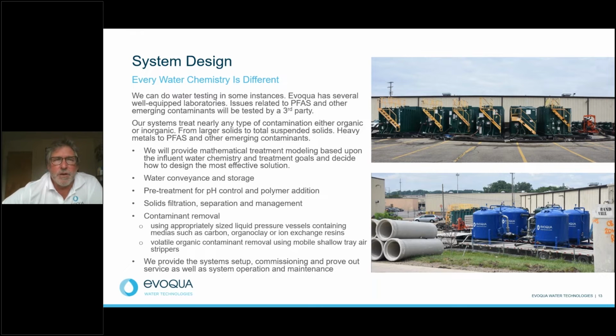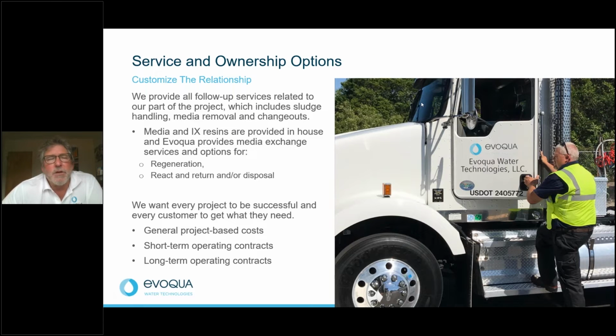And as you know, the water at all these sites is different. I don't think there's any one site that's the same. For a tunnel project, maybe you're just dealing with suspended solids, and all you need to do is remove those solids. So you'll just throw some polymer at it, or sand pods or bag filters, and you've got clean water you can discharge to the sewer. Other sites, you may have heavy metals, you may have gasoline components, you may have PFAS. We're finding it everywhere now. And each one of those constituents that you throw into the mix requires a different set of treatment in the treatment train. So depending on what you got, we'll set it up for you.